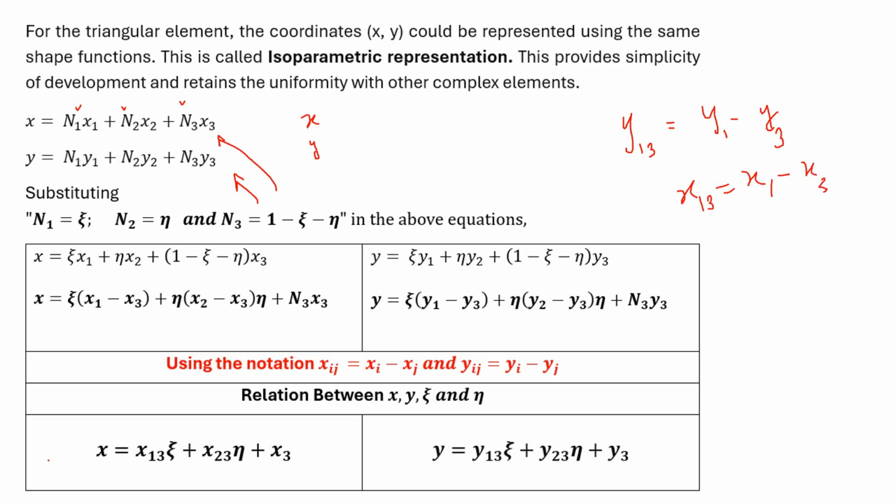So you can see that we find the Cartesian coordinates x, y at a particular point inside the triangular element. So at this point P, the variables are x, y. This x, y is obtained by these two equations, which are connected by x1, x2, x3, y1, y2, y3 and the natural coordinates psi and eta.